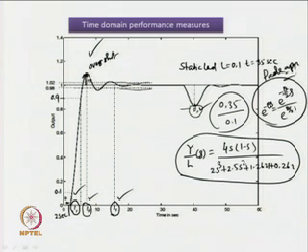Now, using that approximation, the closed loop transfer function denominator polynomial becomes this. As it appears that all the roots of this polynomial are located in the left half of the S plane, therefore, we obviously expect stable disturbance response, or we say successful disturbance rejection by the closed loop system.